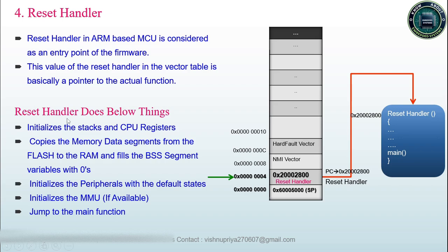So what are the different functionalities your reset handler will do? The first major step in the reset handler is to initialize your stack. The stack pointer has already been initialized, and also we're going to initialize the stack here. What will be the size of your stack? What should be the memory location? All those things we're going to initialize with respect to the stack, and also we're going to initialize the CPU registers as well. That is the first major thing.